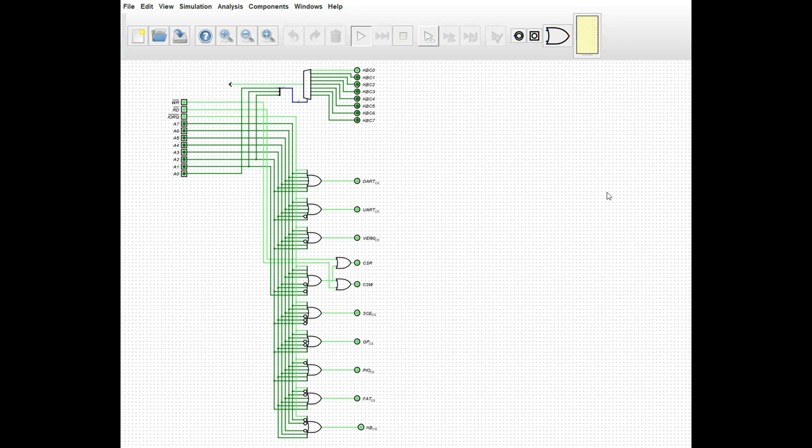So that's it for the decoder today. Kind of a short video, kind of long, probably something that most people don't really need to watch as far as how to construct these, but it's nice to see how to do it in a program such as Digital, which can again export to VHDL, which is very important because, like I said, we are going to be stuffing this into a CPLD. The CPLD is going to effectively act as an ASIC, if you will. So it's nice to have that feature so that we can build very small compact boards that have a lot of stuff going on.